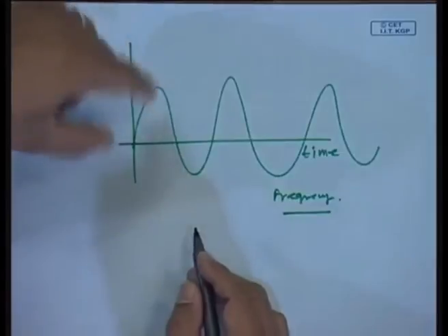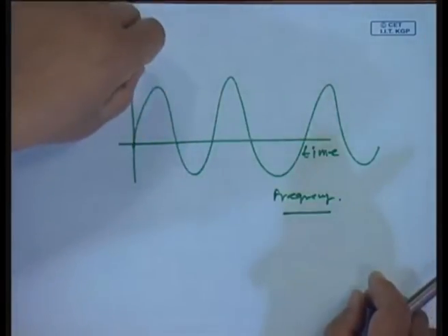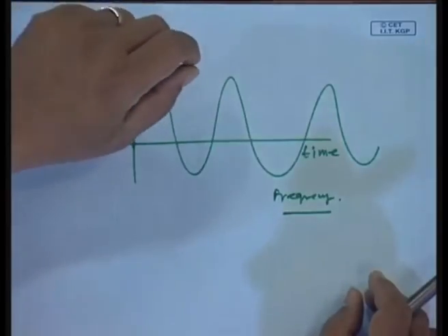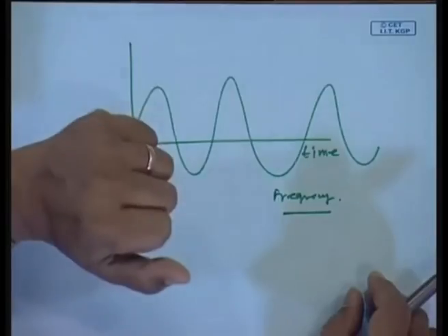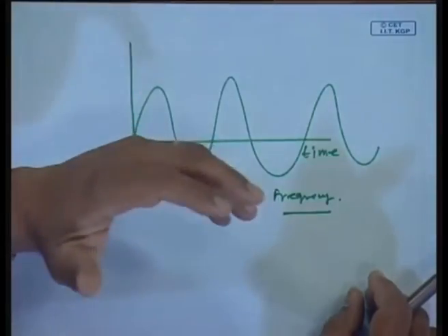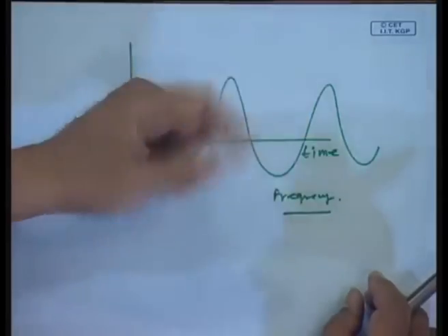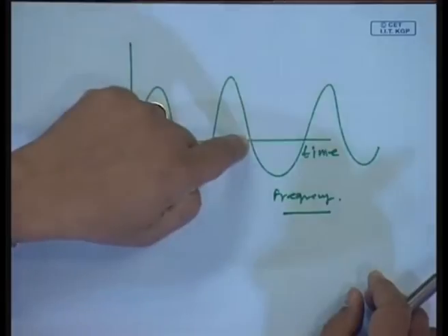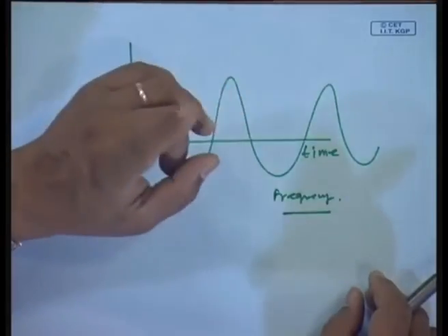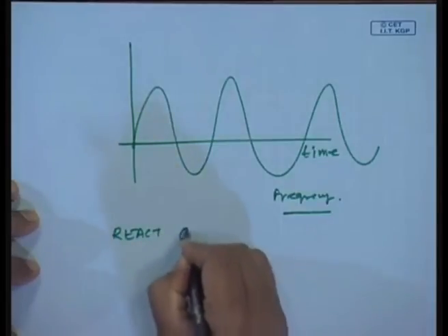Suppose every instant the vibration is changing. I cannot come with a transducer which will measure vibrations only at intervals of 10 minutes. So, I am going to lose this phenomenon, is it not? So, my instrument has to react faster than the quantity or the mechanical parameter which I am measuring. That is very, very important. I use the word react quicker,